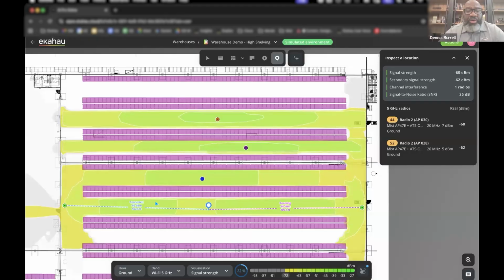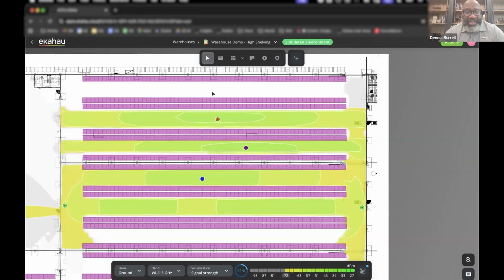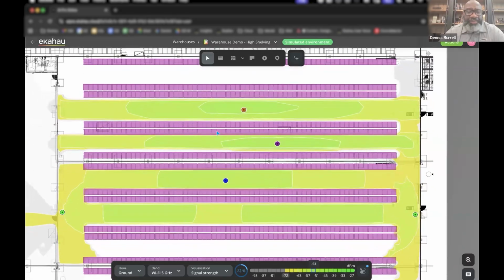So then we go with the antennas mounted on the wall, like you have there, shooting down the aisles. And then you want more of a symmetrical one, because that warehouse antenna that has that 115, 120 horizontal beam width wouldn't work in that scenario as far as being mounted on the wall.